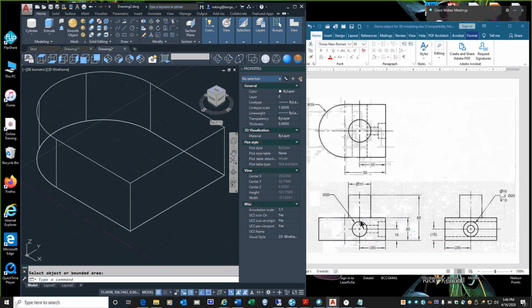Okay? Now, sticking out of the top of it is a cylinder that's diameter 30, and the height, well, if this whole thing's 60, and this is 30, so it's a 30 by 30 cylinder. And that's right at the center of this, which would be 35 units in. So we can track from this midpoint in 35.